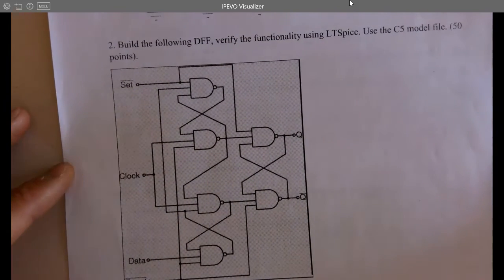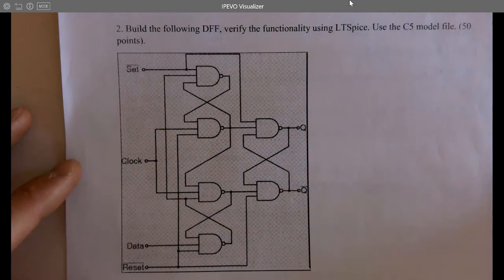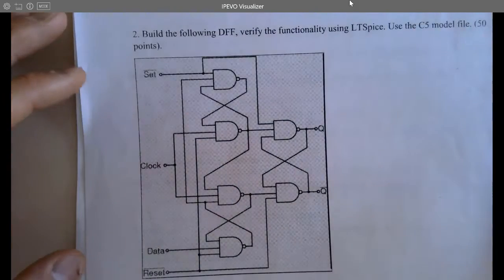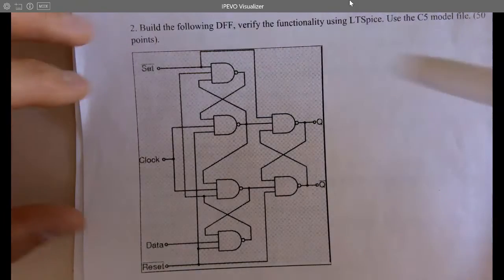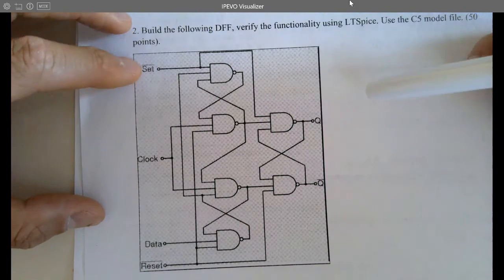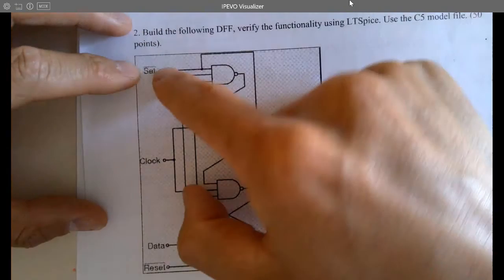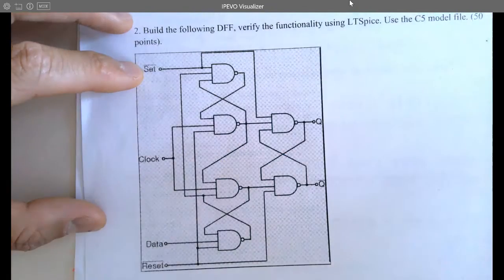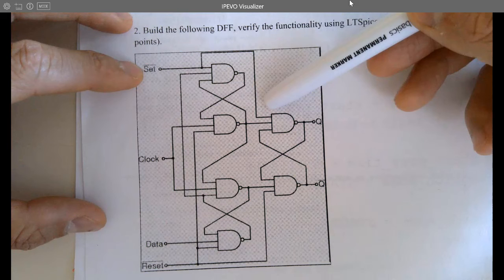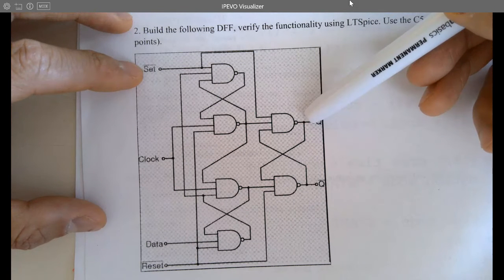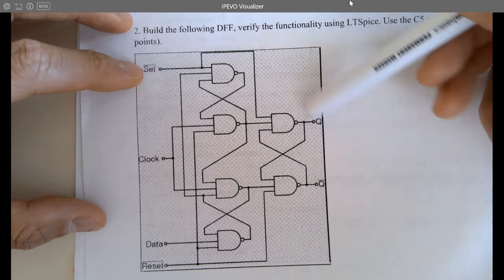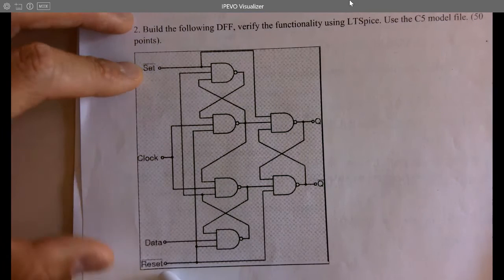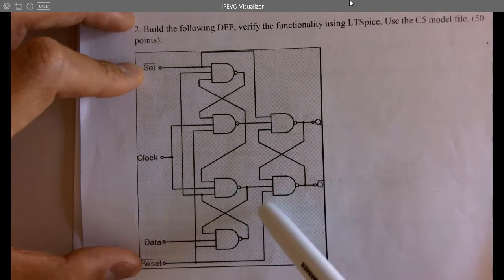First, can we standard reset this D flip-flop? Okay, how do we do it? If we give a 0 here, since you see a bar on the top, which means it's active low, a 0 will be sent to here, and you got a 1, no problem for Q. But are you getting a 0 at the same time here? Whenever we give a 0 here, this one should be 1, so this is not changing anything, right?